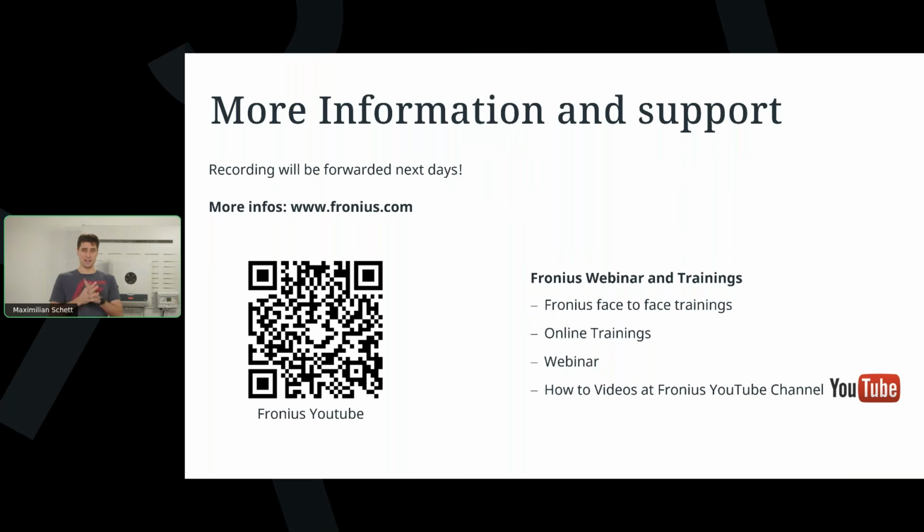We looked at error messages. What can you do if an error message opens? Best case, don't panic. Just take a look at the inverter, open SolarWeb, take a look at the error message. There you find suggestions for what you can do. Just go through them. Probably the problem is already solved. In many cases of those problems, there are two things you as a PV owner can do. First of all, you can install an update, and secondly, you can also restart the system.